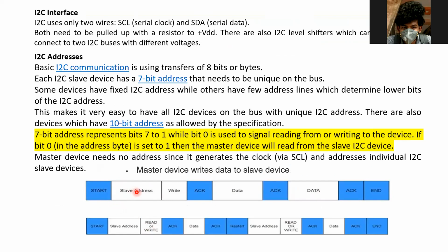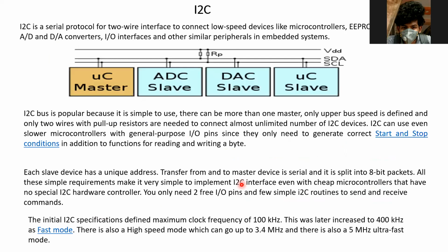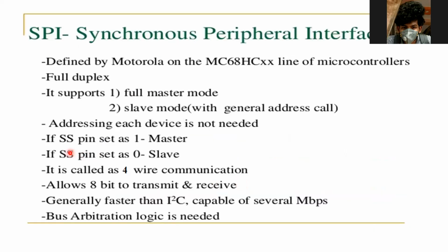Then my slave device. So I am telling your register number, Kritika, register number 47. She's obeying me. Then automatically she can understand her register number is 47. So every time I want to communicate from master to slave, I will send the address, then it will acknowledge, then I will send the data. That is the concept.